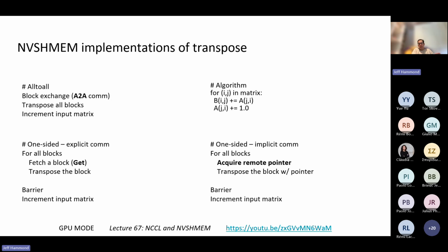And so what you get here is, if you do the performance model breakdown on transpose, part of this is moving across the NVLink network at, I can't remember what it was, 3 terabytes a second aggregate, I think, and then it's like 24 terabytes a second aggregate to all the 8 GPUs' memory. So it's like an order of magnitude difference, right?